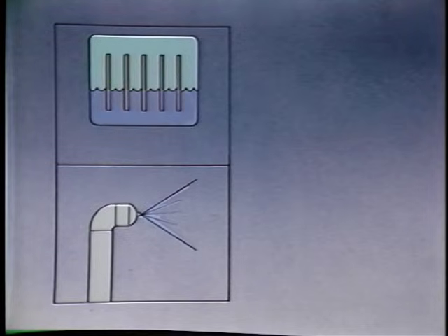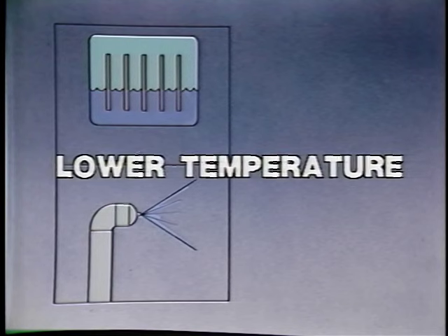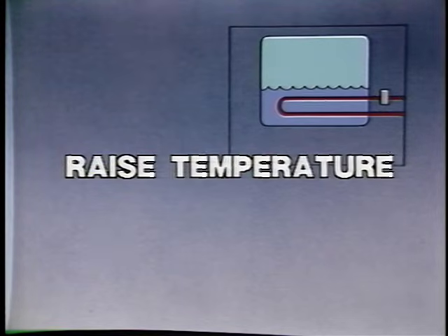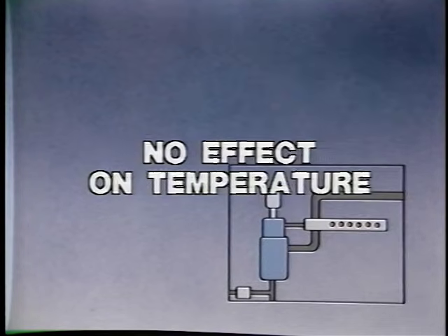In both the wetted element and water spray method, that heat is supplied by the surrounding airstream, lowering the air temperature of the system. The evaporative pan method provides most of its own heat of vaporization, therefore raising the enthalpy and slightly affecting the air temperature.